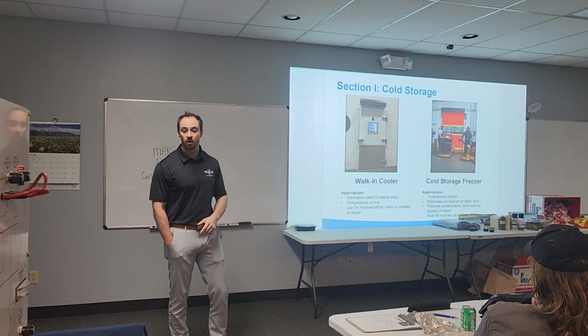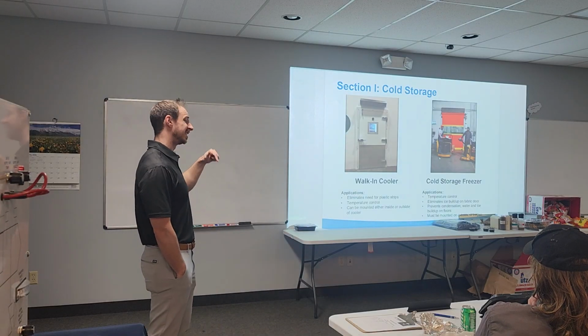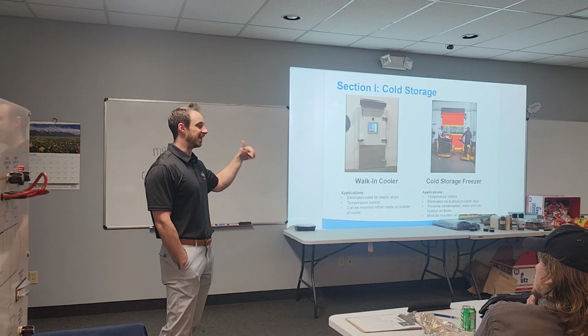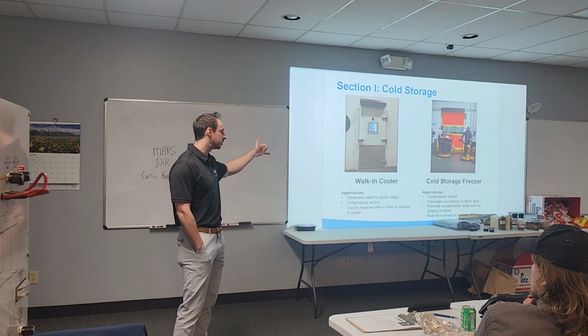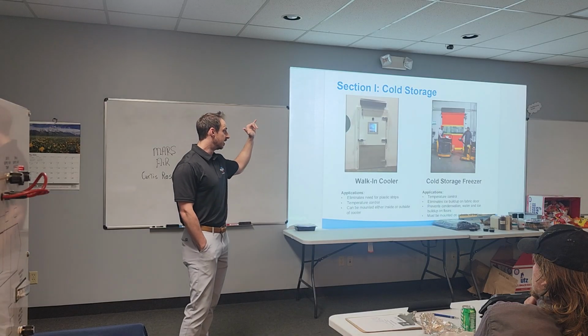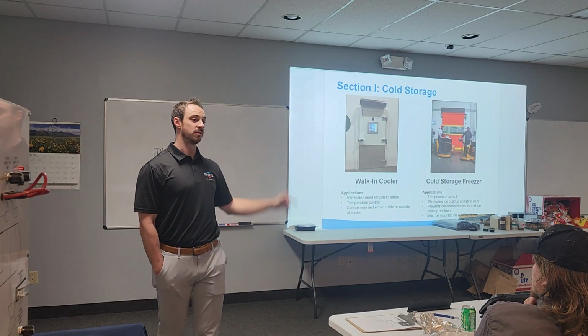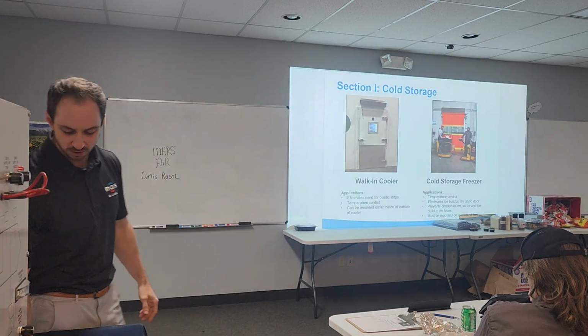Freezers, the only note I like to make there is they can't be installed on the inside of the freezer. It pretty much just creates a snowstorm. So coolers you can kind of do either. We always recommend the warm side if you can, but freezers have to be installed on the warm side. So just a note of that.